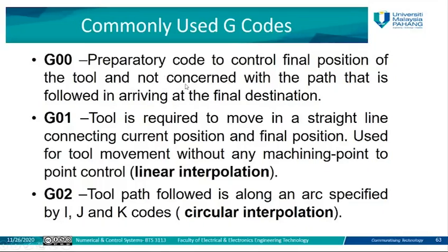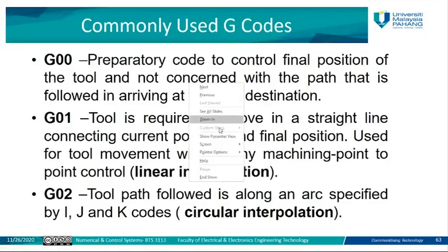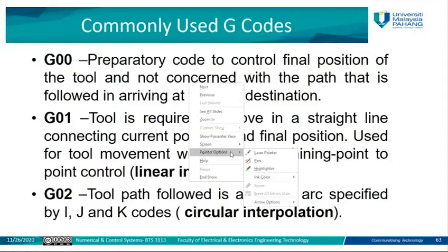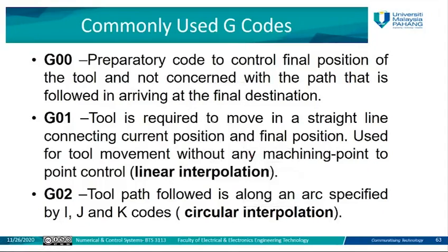Or the most common G code, and with some examples to show how to use this G code in CNC coding. So the first one is the G00, and you already saw this before. We said G00 is used for the fast traverse, to move the spindle from the source point to the destination point without conducting any task. It means just move.